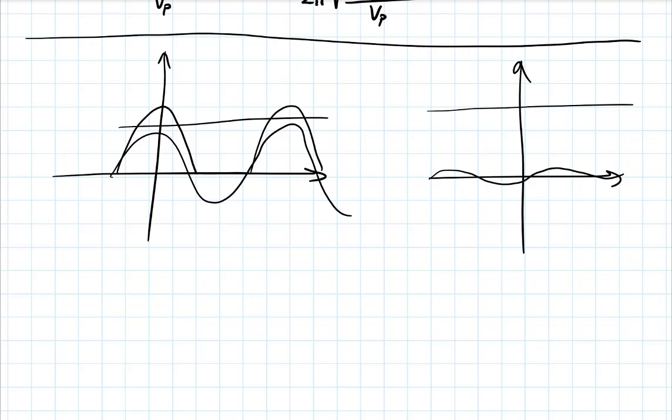I have thrown away most of that frequency and kept, in this case, the zero frequency or DC value. So I've filtered things out. This is what you would call a low-pass filter. It has allowed the passage of the very low frequencies, meaning, in this case, the zero frequency, the DC signal, and has limited greatly the passage of higher frequency components.